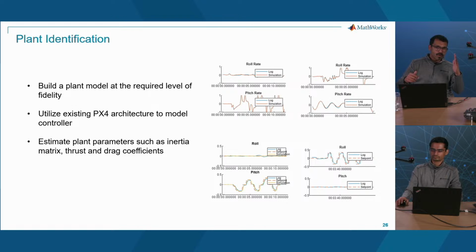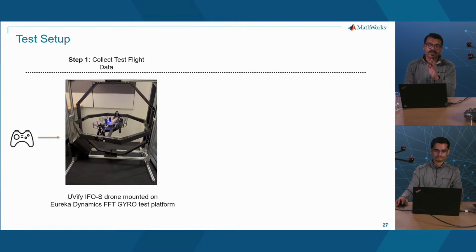So you set a lower min and a higher max, and then Simulink will automatically sweep through all the set of combinations to give you the lowest error, which will tell you what a more accurate value for these coefficients would be. We actually have a demo that we built just with that.